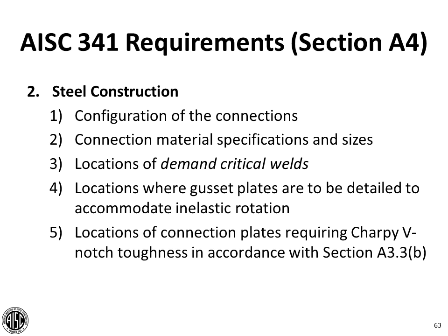Larry talked about demand-critical welds. I think he may have been a little kind in his explanation of why sometimes drawings show all the welds as being demand-critical welds. My experience is that sometimes engineers just get confused and they throw up their hands and say, well, I can't figure out which ones are supposed to be demand critical, so we're going to make them all demand critical welds.